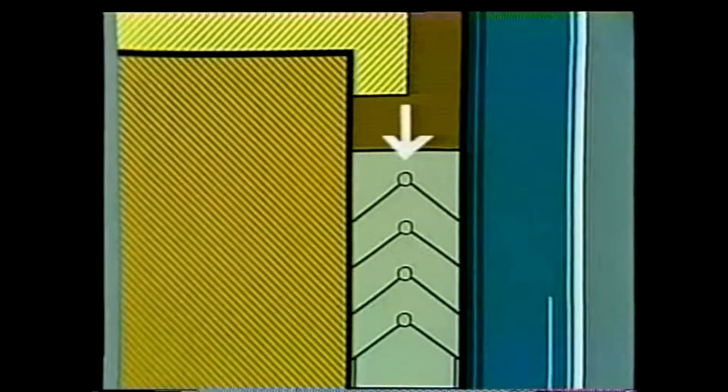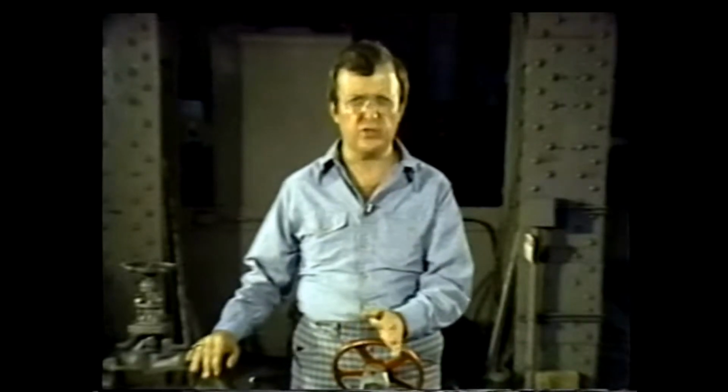Around the outside of the hollow tube is a vacuum jacket, which acts as an insulator. Thermal foam is placed at the top of the hollow tube shaft to provide insulation. The valve is packed at the top, or warm end of the valve, with chevron packing, or an O-ring, to ensure that there is no leakage by the valve stem.